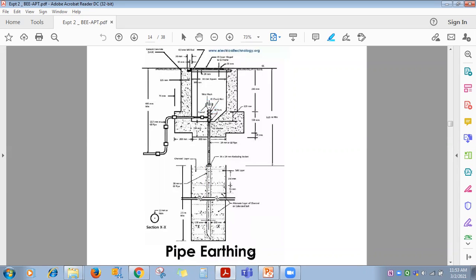Now, to minimize the earthing resistance: use galvanized iron or copper, and select the dimensions of the plate or rod so that resistance will be less. Use alternate layers of salt and charcoal so that it holds moisture for more time and earthing resistance will be less. Through this funnel you can pour water to increase moisture content under the ground. Rather than using a single plate, suppose 4 ohm and 4 ohm are connected in parallel, what will be the resistance? 2 ohm. So rather than a single plate, you can use a number of parallel plates wherever it is not possible to increase the depth.